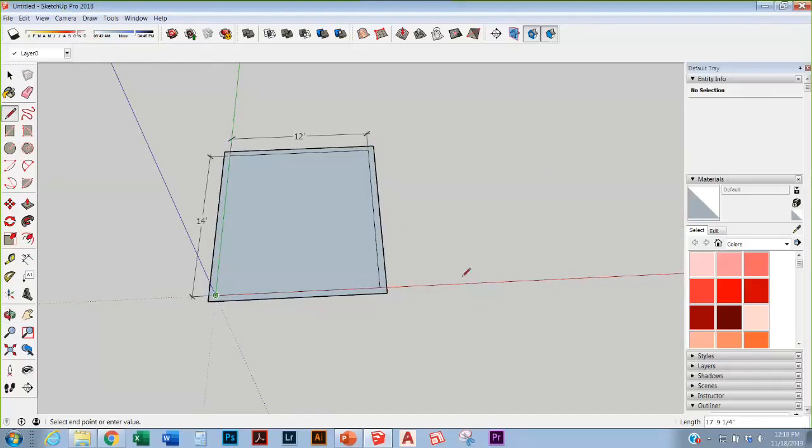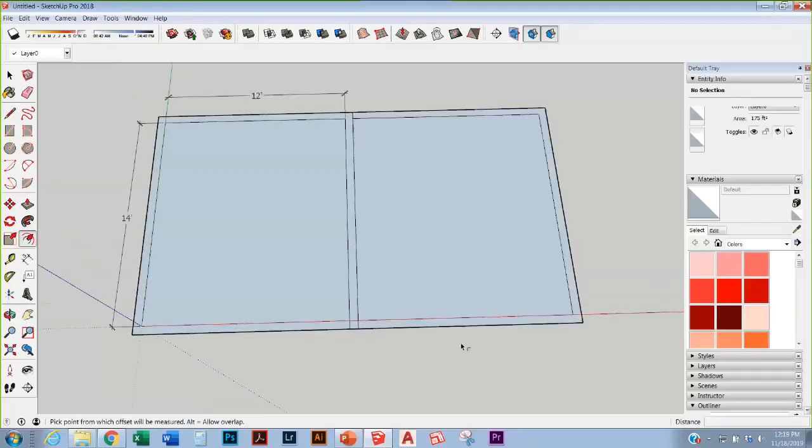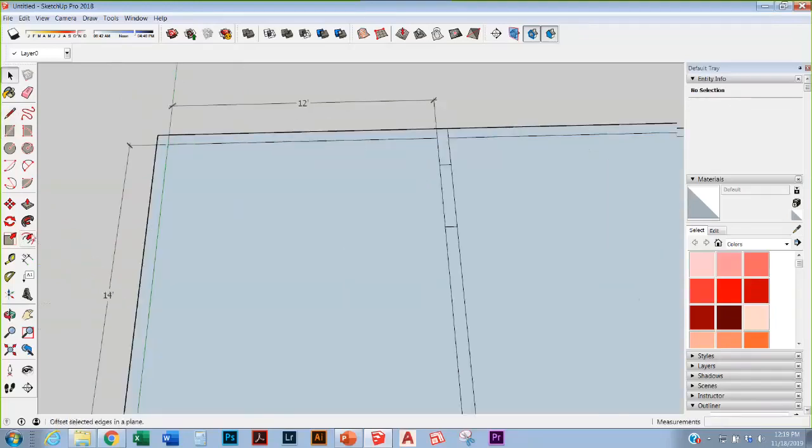So what I would do is I would come off this wall, and this following wall, say, is 25 feet away, whatever it is with your laser distance meter. Now, why this is important is anything over 25 feet starts to become really, really difficult to measure with a tape measure. That's why I recommend using a laser distance meter. So again, you can start to come here and then boom, start to build out your rooms really, really quickly, okay? And this is where we can start putting in doorways. You can come here and see, boom, this is 36 inches, comma, 6 inches. So that's going to be a 36-inch doorway. We can then put a measurement here, just like so, and then move this door wherever we want, right?